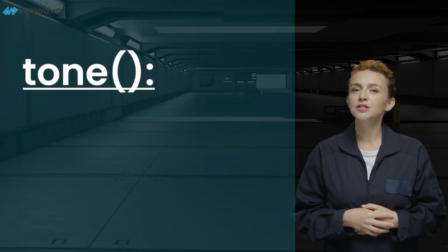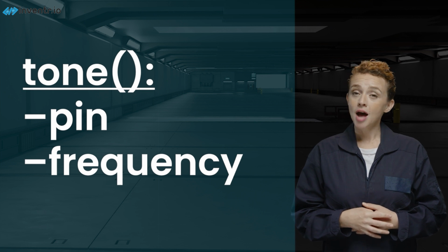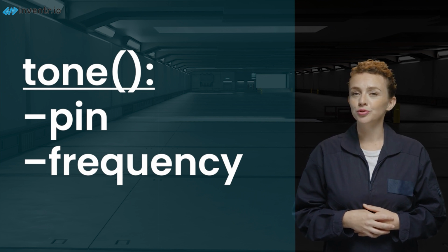Luckily, sending those tones is made easy with a built-in function called tone. Tone takes two parameters, the pin and the frequency you want to send. Optionally, you can also put a third for duration.